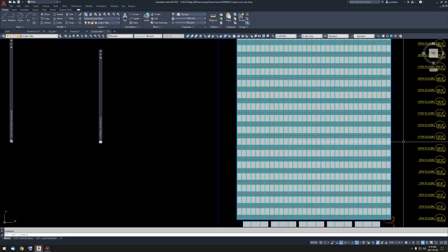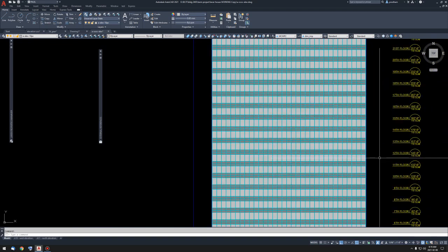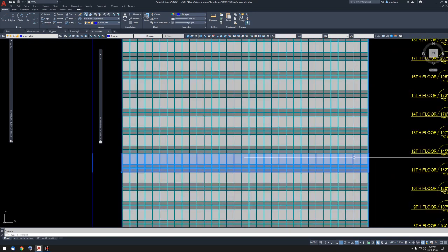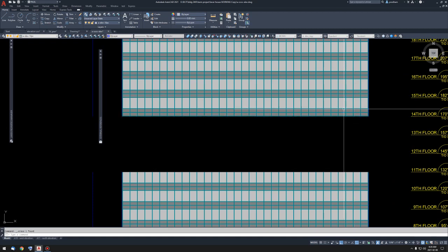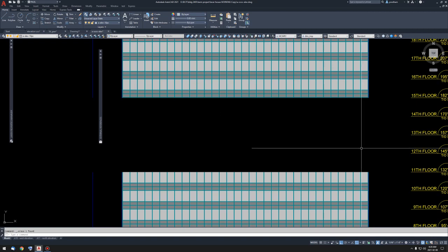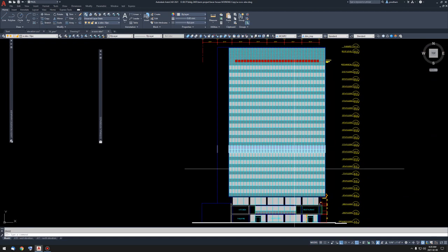If you look at this building enough, you can see that it's essentially like a wedding cake. It's just layer on top of layer, or floor on top of floor on top of floor. So each floor is a block. Each floor is a block. That's exactly the way I want you to build it. I've had people do it differently, where they've even done dynamic blocks and then copied them up. But essentially all I want is each floor to be a block, for the tower.